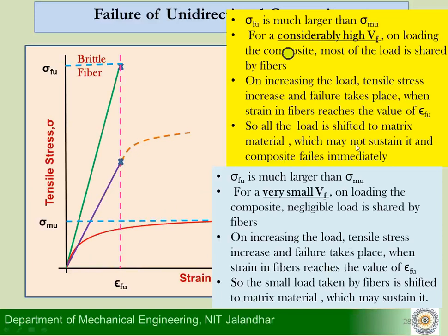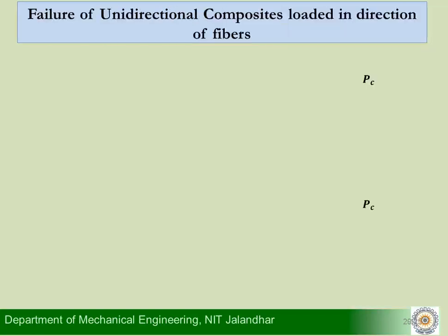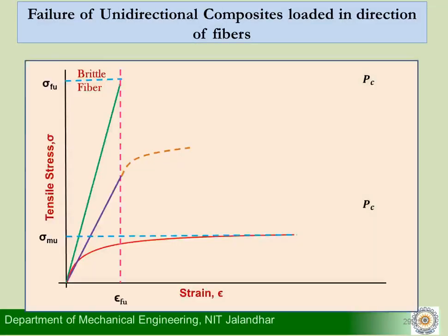So for high volume fractions, the moment fibers break, you may see that the failure of the composite is immediate. For very small volume fractions, the fibers break, but because they were carrying very small load, the matrix material may be able to take that load to some extent, and the failure of the composite may not happen immediately. Okay, let us look at it in a different way.